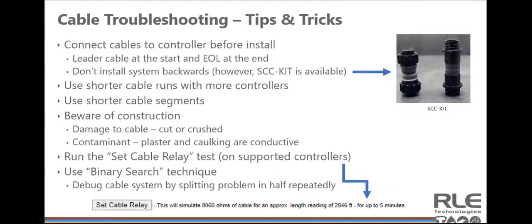What happened? Fire caulking was installed around the cable, which is conductive and will just put the system in constant alarm. So this is a pretty costly mistake to make, but the good news is there's a pretty straightforward solution. We also provide non-sensing cable, so if you just run a short bit of that cable through a section you know is going to be fire caulked, that'll solve that problem.